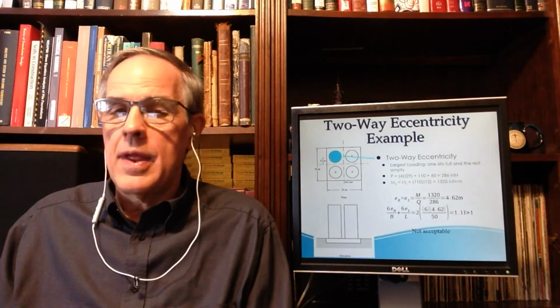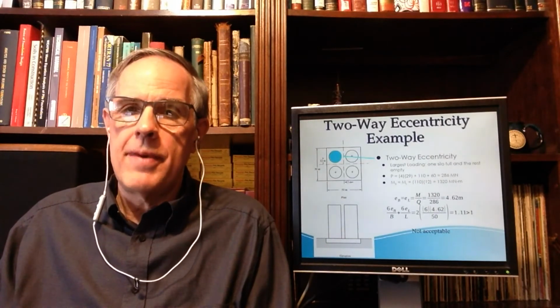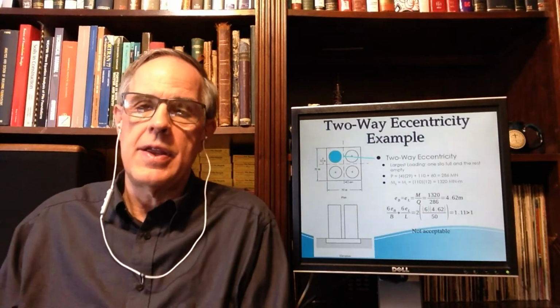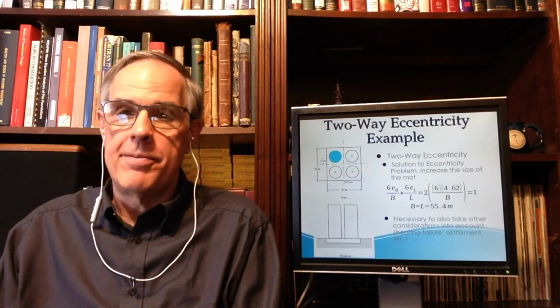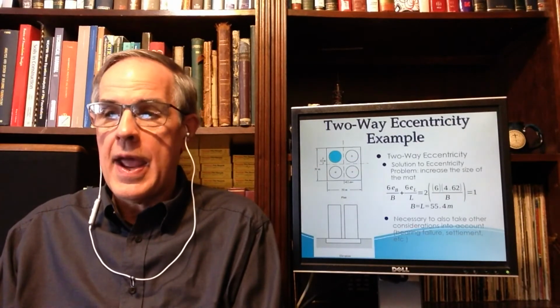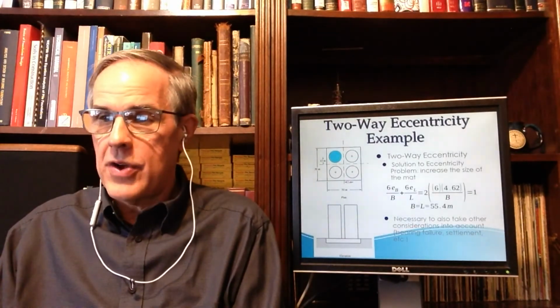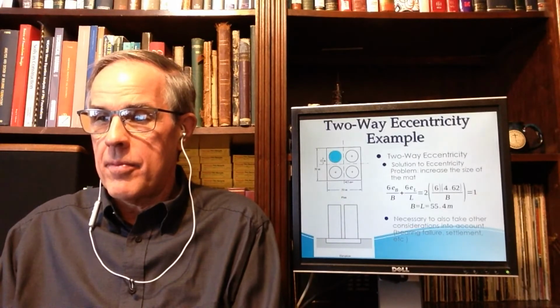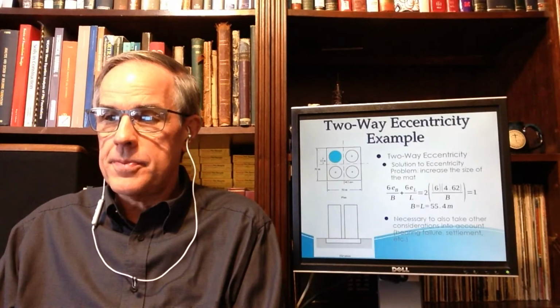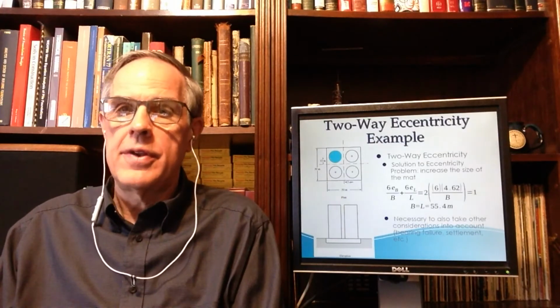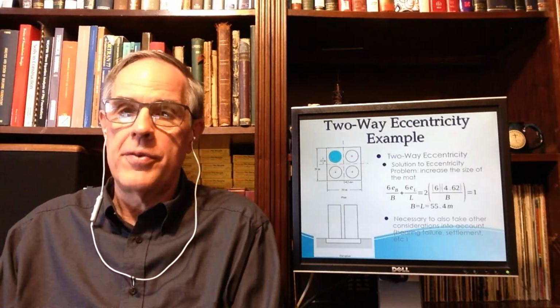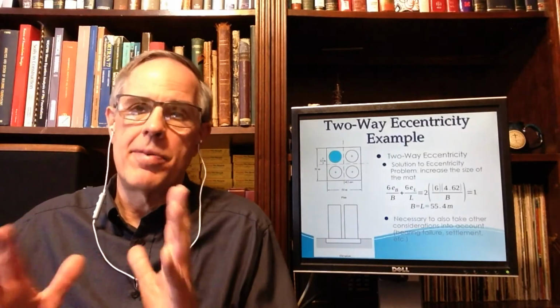Now, increasing the size of the mat does increase the weight of the mat. And that would definitely impact bearing capacity and settlement. However, the eccentricities will be altered; I've got a chicken or egg problem.